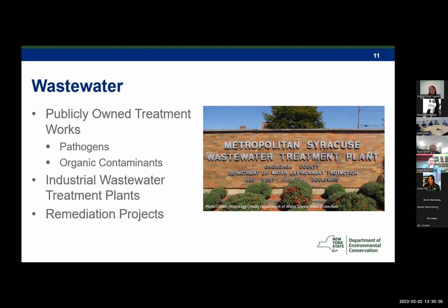So Dilara's work has shown that electron beam treatment can effectively degrade a multitude of organic contaminants. However, these compounds are not typically the target of publicly owned treatment work discharge permits. In addition to the degradation Dilara described, this type of treatment can also disinfect wastewater. And one study by Maruthi et al. showed that low doses of electron beam treatment within the range of dosages used in Dilara's study were effective at reducing total bacteria counts, total coliforms, and total Salmonella Shigella counts in wastewater.